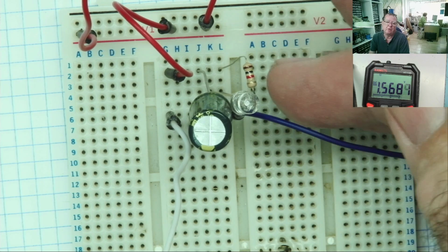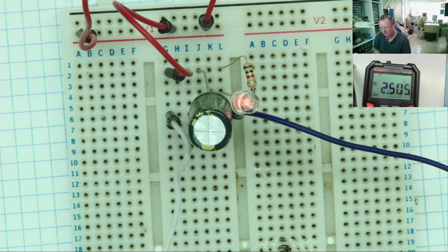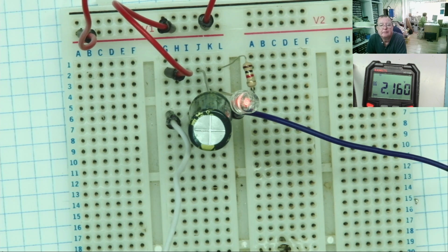In the meantime, while we've explained a few of the stranger properties that other people don't ever tell you about, I've put a 1000 ohm resistor in. So this is a bit more than twice the size of the first one we had. So we should know that the capacitor will charge up. And when I take the power off, it will now discharge slower because I'm drawing less current from it. Okay? Taking quite some time.